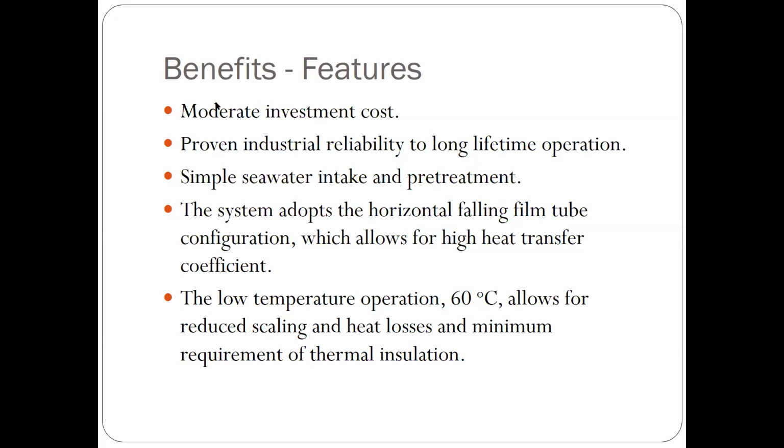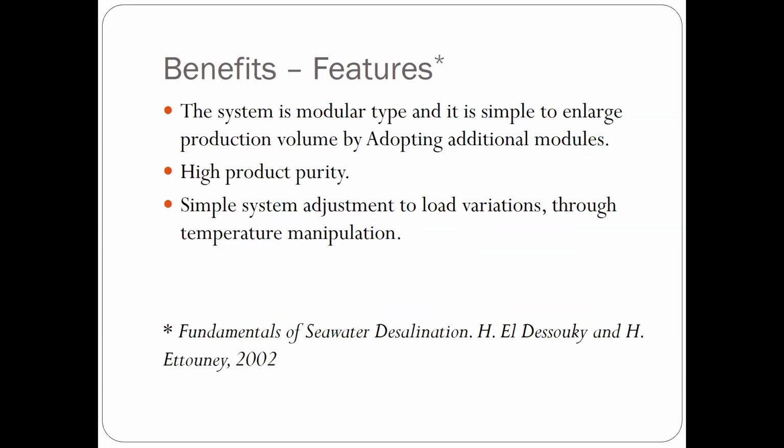Horizontal falling film tubes are there. Low temperature operation, 60 to 65 would be the limit of the temperature for the sprayed seawater. And accordingly, you can have less scale formation in this unit.